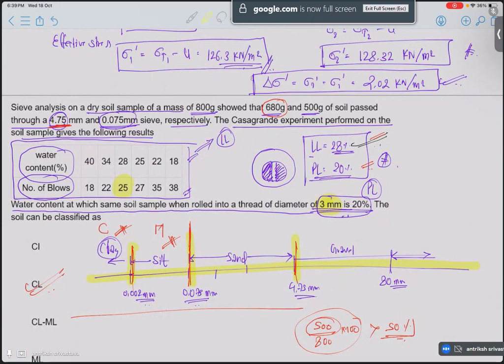So 4.75 is the threshold, and usually we don't get the grain size distribution above 4.75, because then it is just gravel and cobble. So usually the questions are not framed with that big of a size distribution. You need to remember that from 4.75 to 0.075 mm we have sand, and the threshold between clay and silt is 2 micrometers or 0.002 mm, whichever is comfortable for you.